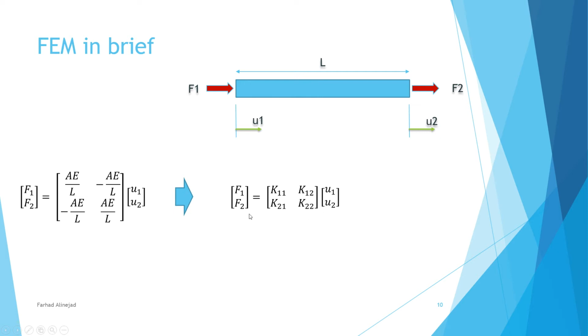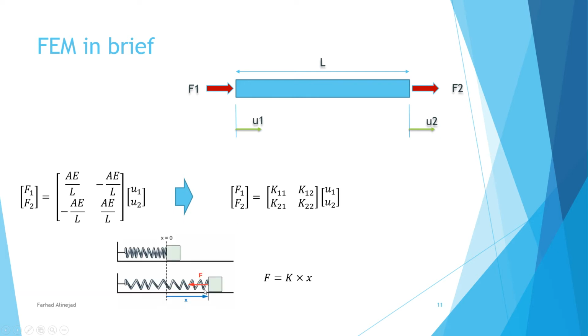And this equation may recall something in your mind. If you can remember Hooke's law, the spring and the force, you may remember that we connect the force applied to the spring with the displacement by these formulations. And here K is the spring constant, and it was connected to the material and the geometrical properties of the spring. And here we have the same thing. It is very similar. We have force, we have displacement, and we have this matrix in between.